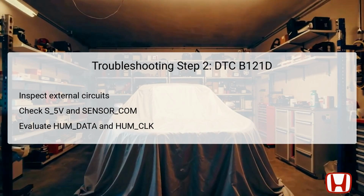Use a multimeter to confirm continuity along these wires. For a thorough evaluation, check for both open circuits and any shorts to ground, which can lead to further issues and miscommunication in the data being transmitted. If any anomalies are detected in the circuitry, repairs or replacements should be addressed immediately.